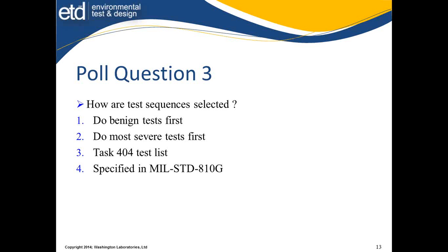Should I do an evaluation on a before and after event? For example, an immersion or rain test, I might do it before dynamic testing like shock and vibration, etc. And then repeat it after to verify that there was no damage, that we know it was good, do the damage test, and then verify that it stayed good.